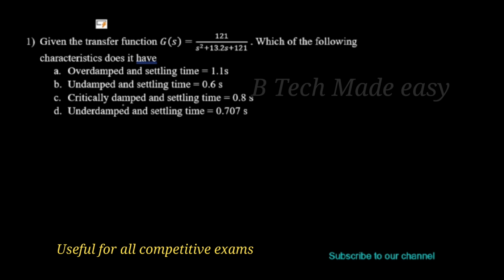First question: given the transfer function G(s) = 121 / (s² + 13.2s + 121), which of the following characteristics does it have? First option, overdamped and settling time equal to 1.1 seconds. Second option, undamped and settling time equal to 0.6 seconds. Third option, critically damped and settling time equal to 0.8 seconds. And the last option is underdamped and settling time equal to 0.707 seconds.